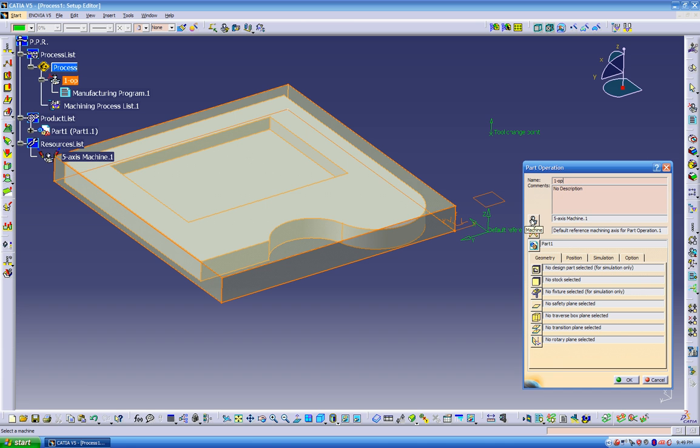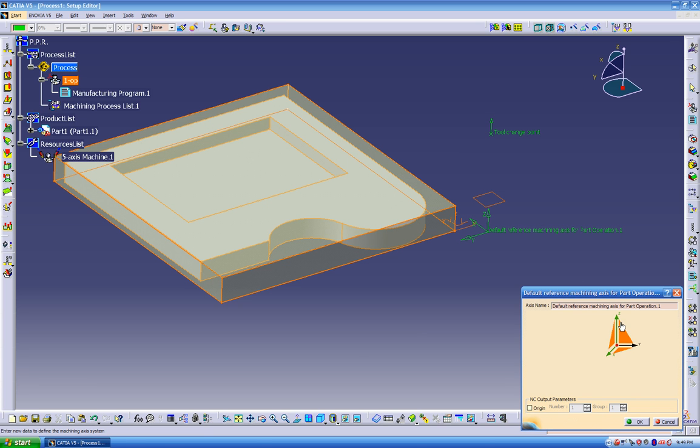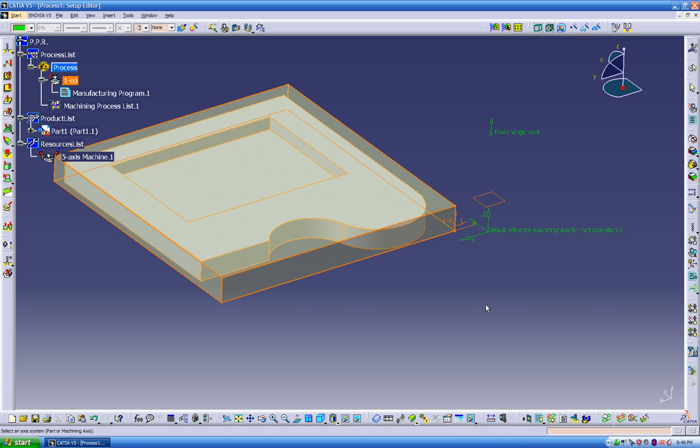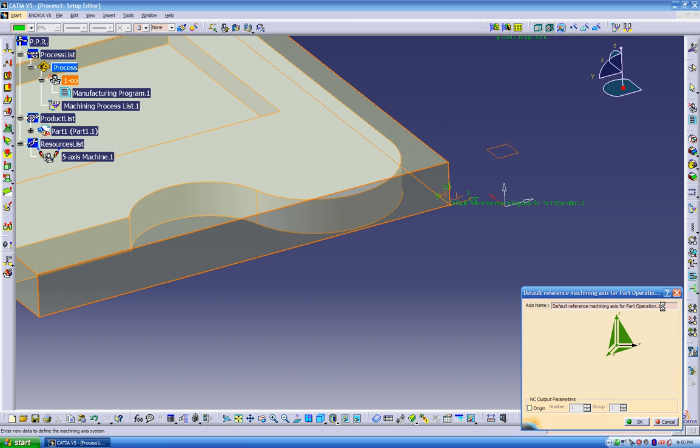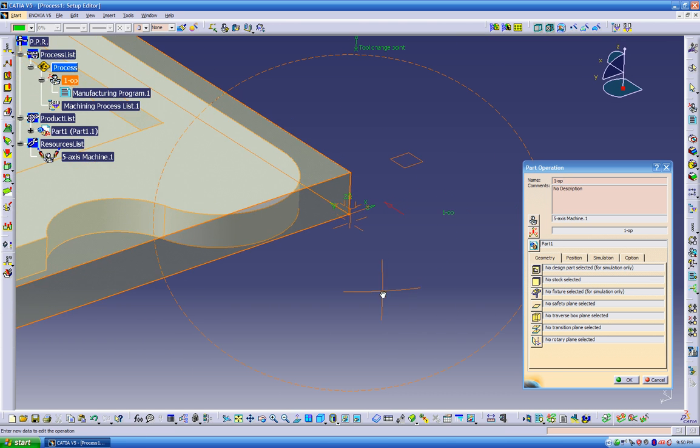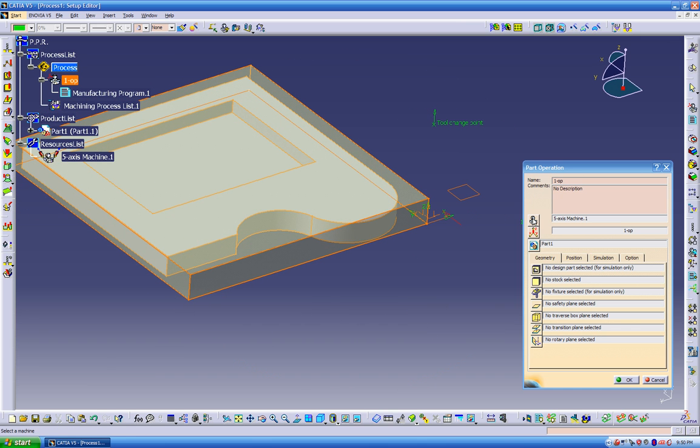That was our machine. Now second icon, it's our axis. So we're going to click on the axis. We can click anywhere on the red area, and it's going to ask us, on the bottom over here, to select an axis system. So I'm just going to select this axis, and automatically it snaps into the new position. And I'm just going to call it first op. So this is our first op axis. So we define the machine, we define the axis.